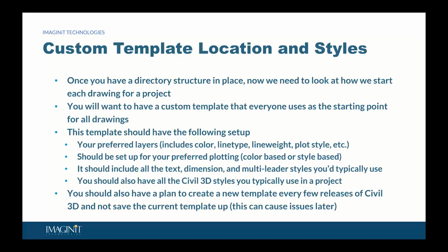So you should also have a plan to create a new template every few releases of Civil 3D and not save the current template up. What I mean by that is that every time the DWG format changes, you always want to go through and create a new template.